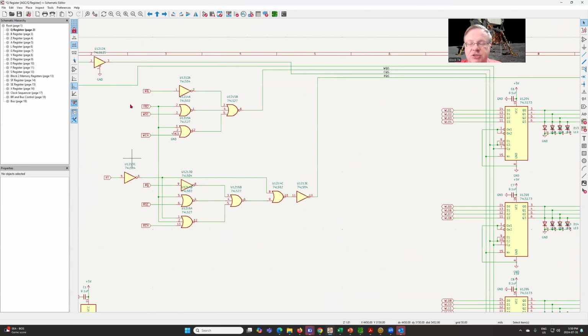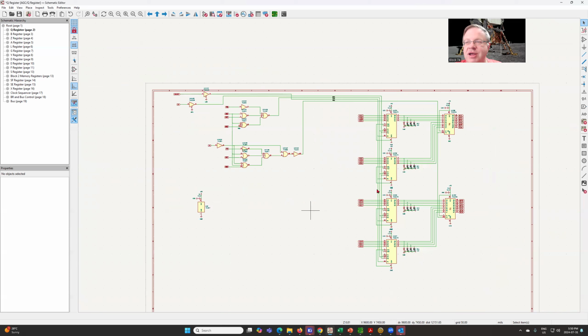And like I said, this is so that some of the machine instructions that are applied to the I/O channels can be applied. So basically, the queue register becomes a valid source and destination for those channel instructions. As a result, that makes it quite a bit simpler on the queue register. We actually removed 6 chips, and the logic was simplified a little bit as well.